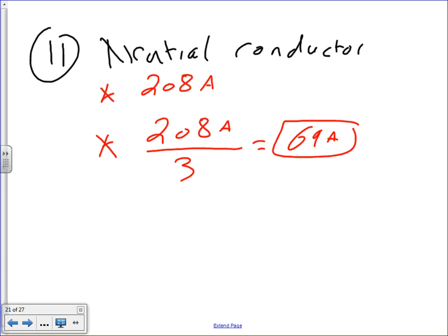No, because for the neutral load, it's highly unlikely, guys, that current will all be in the neutral. Remember, we're sizing a neutral. Half of it is going to be in phase; this will be coming from phase A and phase B. The only way the neutral can see it is if you turn all phase A off, and only the phase B load is there. How often would that happen? So highly unlikely, I wouldn't. This is really even exaggerating.